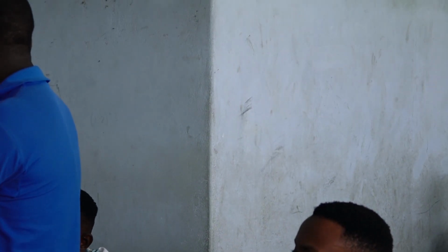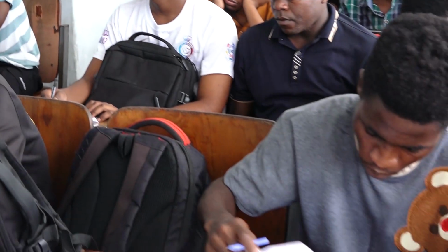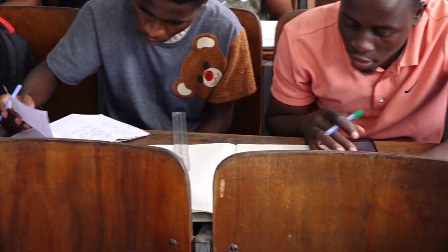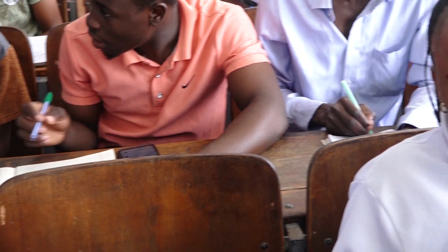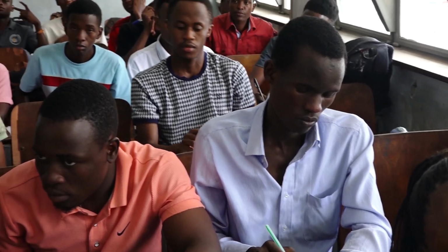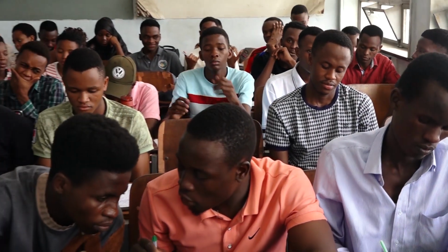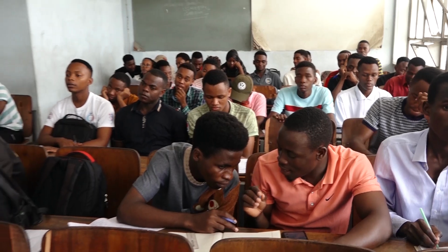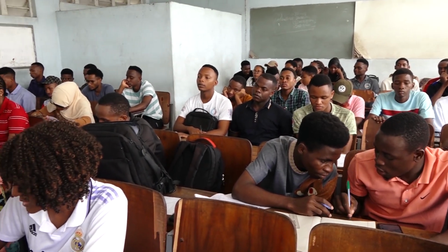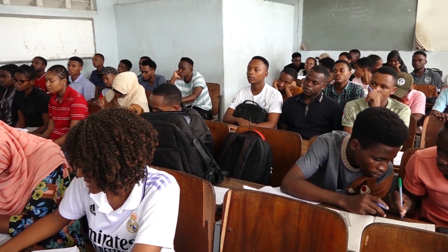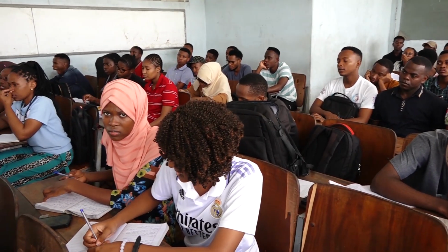I've written there A0 up to A4. A0 is a pin name. It's not a pin number. Tell me the number. Pin number 1 up to pin number 5. Very good. And hence the first step, connect the 4 remaining address pins to the common ground of the DC power supply. So give me the number of those 4 remaining address pins.